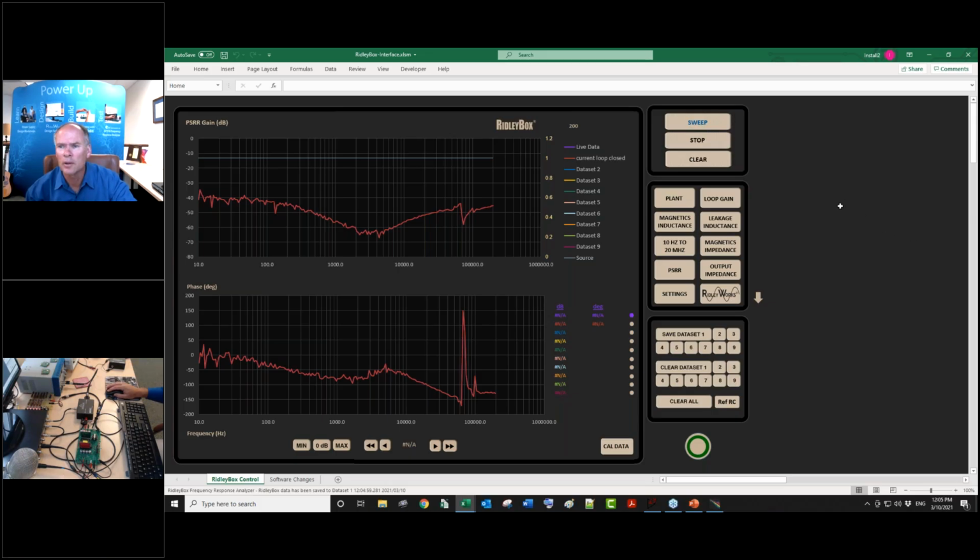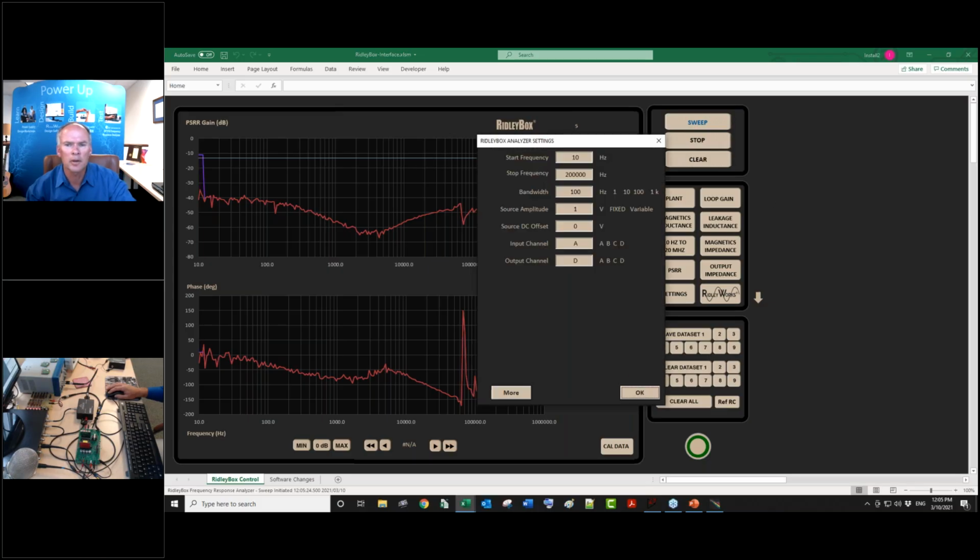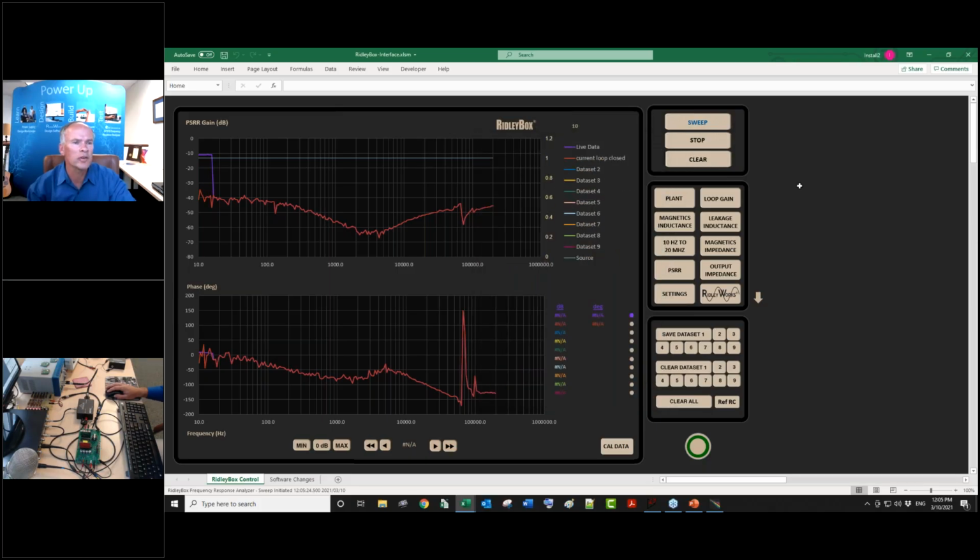Measure again. Sweep initiated. It should be a clean measurement because it's going to be a much bigger signal. Okay. Oh, we're only using 1 volt here. I'll make sure I change that to 4 before I measure the next one. Okay, so now we're going to see just the gain through the LC filter, and it's multiplied by the duty cycle. That's what that minus 10 dB is.